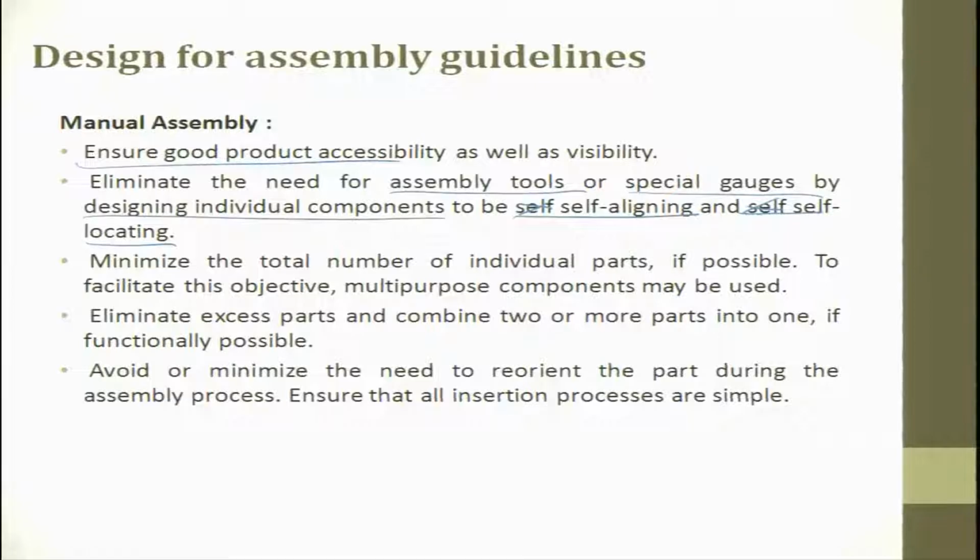Minimize the total number of individual parts if possible. To facilitate this objective, multi-purpose components can be used. So, eliminate excess parts and combine 2 or more parts into one if functionally possible. So, here what they say is, instead of having a shaft, then a hole, then you have a projecting shaft.